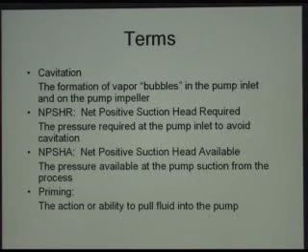NPSHA is the net positive suction head available. That's the pressure available at the pump suction from the process. And priming, and that's the ability to pull fluid into the pump. We'll talk about priming first.